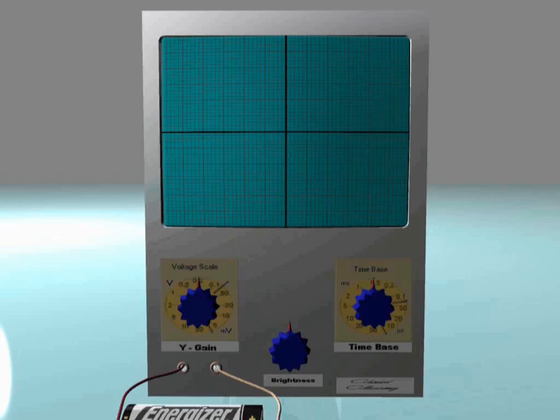These examples will explain what happens inside the CRO by applying different signals on the Y input. Remember that we said before that the signals to be studied are applied to the two openings of the Y input, which applies the studied voltage to the Y plates.